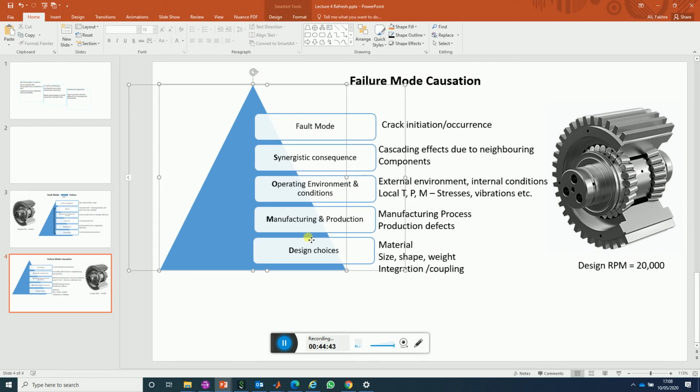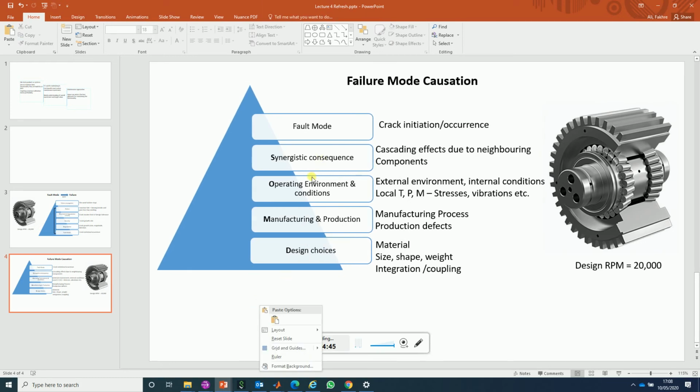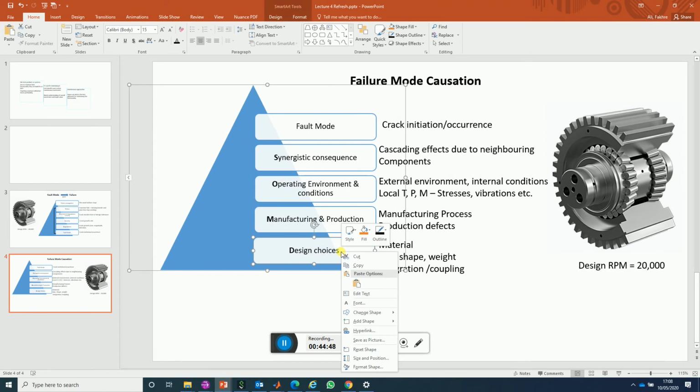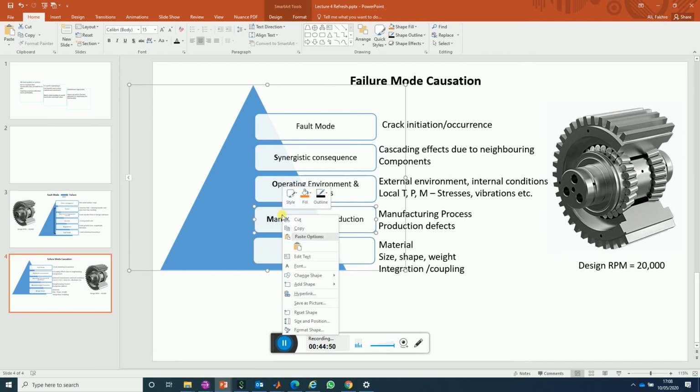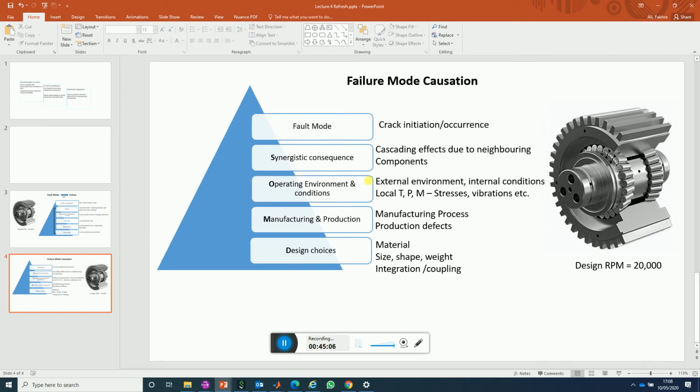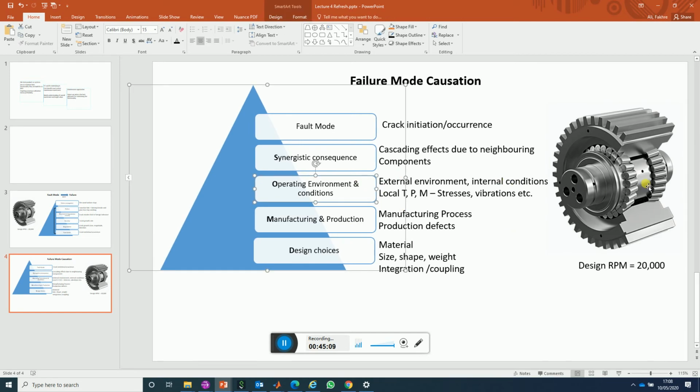Mostly you would want to then, in this case, say, right, design is not properly done, there is high residual manufacturing error, and the operating conditions are not what this thing is designed for. So the whole thing is messed up in this case, right? You would be very much tolerant and say, look, the fact that this crack is occurring is because this thing is now operating in a high stress environment, and that is usually because there is lack of lubrication, so we need to just provide more lubrication to it.